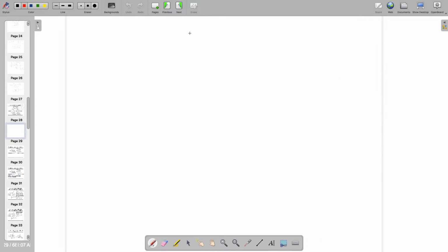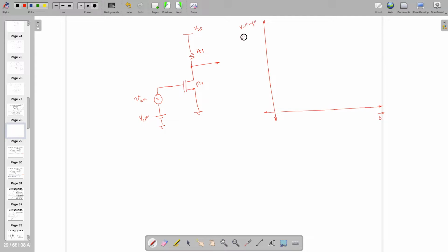So if you understand the thing, if we are looking at only one part of the circuit, single-ended, which has VCMI and there is V in, with respect to time and voltage amplitude, if I am feeding this kind of signal where this is VCMI and input is like this, the role of this particular DC line is to make sure that this transistor is in saturation.